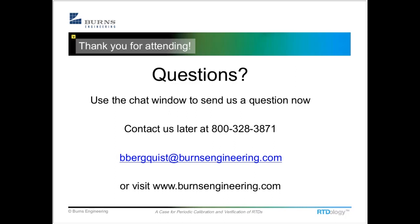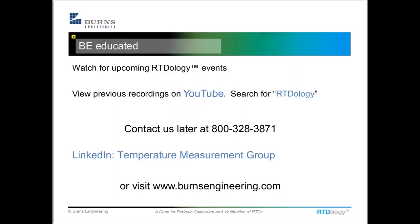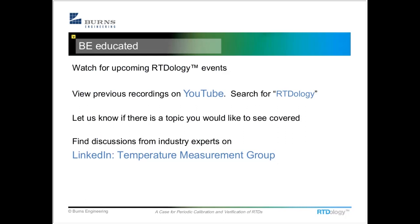Okay, great. One additional question here. Are some RTD constructions more physically robust than others? What RTD should be used in industrial plants where some vibration is likely? When we look at the durability of RTD probes, there are coil sensing elements, and then there are thin films, and some manufacturers will differentiate between those two. And if the thin films are packaged correctly, they can be very durable.